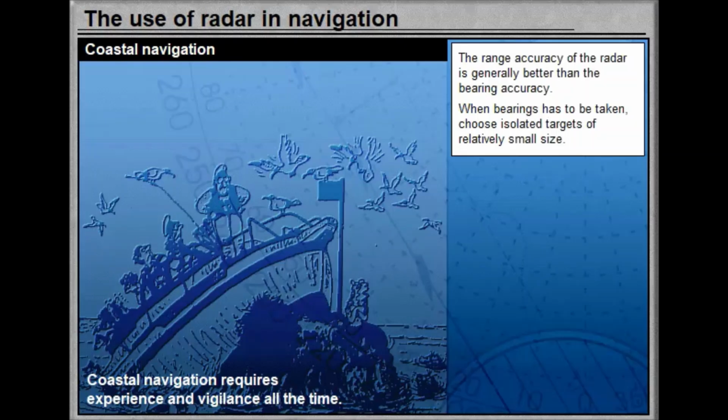Better use of the radar as a navigational aid can be made near the coast. As reflecting conditions become more favourable, more accurate information becomes available. When taking a position fix by radar, one should remember that range accuracy is generally higher than the bearing accuracy. Radar position fixes, based on 3 radar ranges, are normally very accurate. In some cases, bearings must be used.